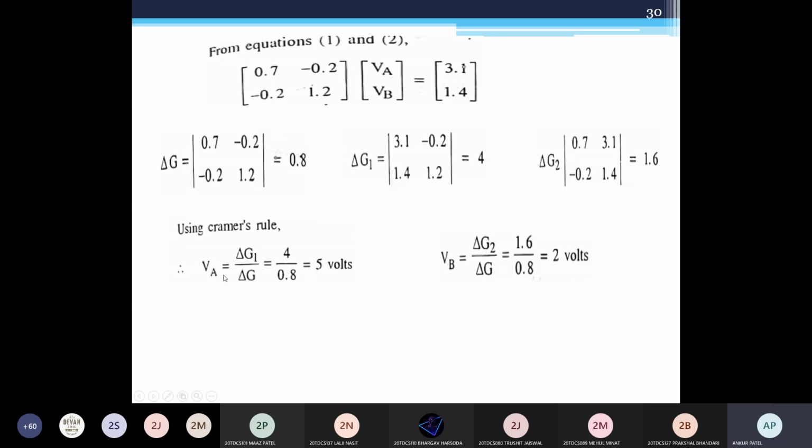Wherever node A is connected, according to that branch, you need to consider it in terms of equations. Same for other nodes, and you have to apply KCL accordingly. If you miss any branch that is connected with the node, then you will get the wrong answer.